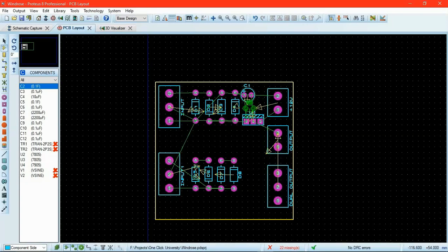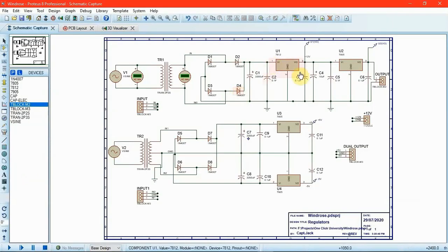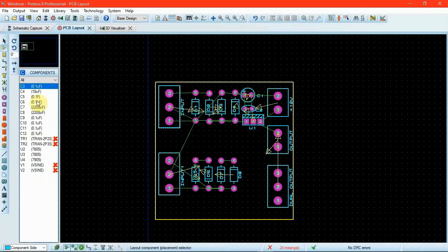Most of the time that is consumed when making a circuit is while deciding how to place the components, because placing the components is very important when we're making a circuit. We are to follow the rules to reduce the space. So now we'll place the other noise capacitor, and another filter, the filter for the 5-volt regulator.